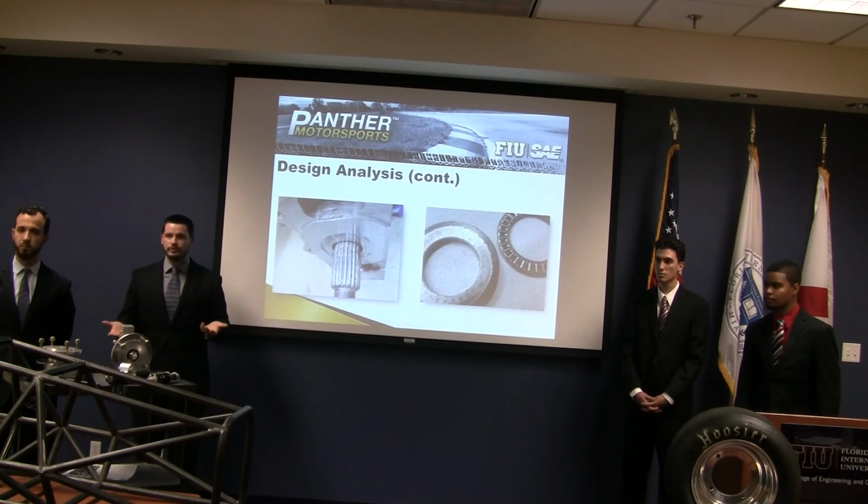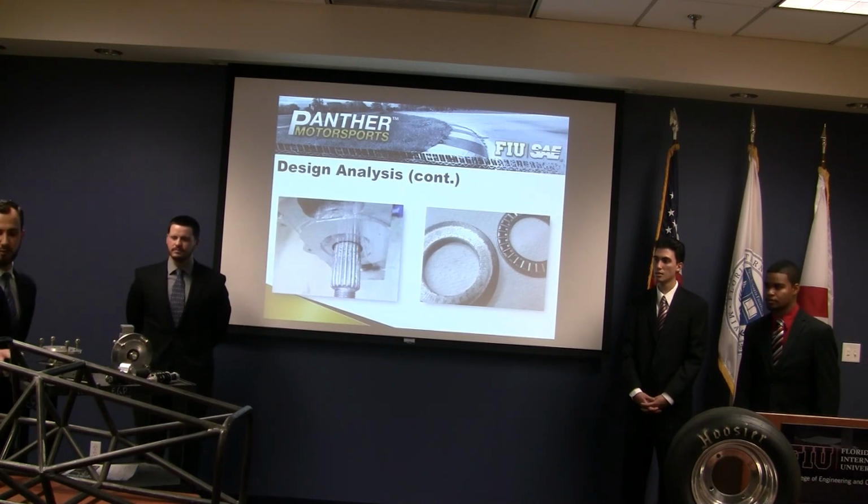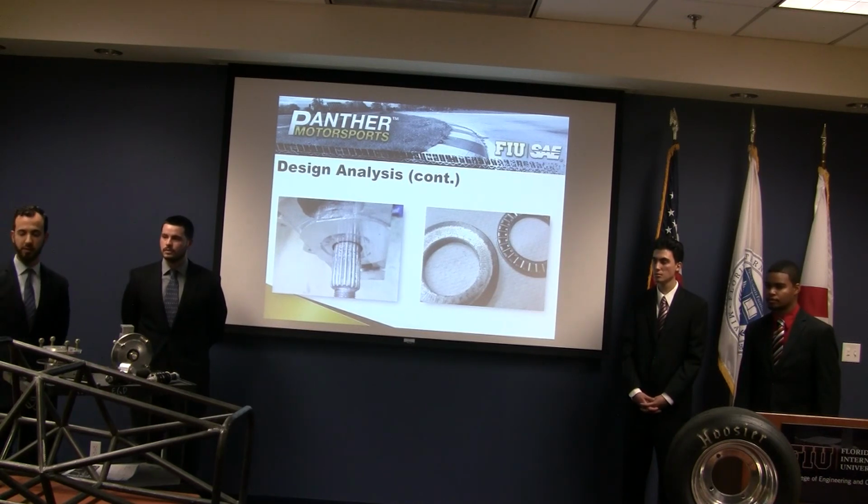And of course, if you pass, they continue and do sonogram testing on your welds and on every structure. They've seen so many that they can, by eye, basically say, well, this is a little weird. The main ones they check are the 0.095 wall thicknesses of the main roll hoops, which is what will prevent you from buckling under a roller.